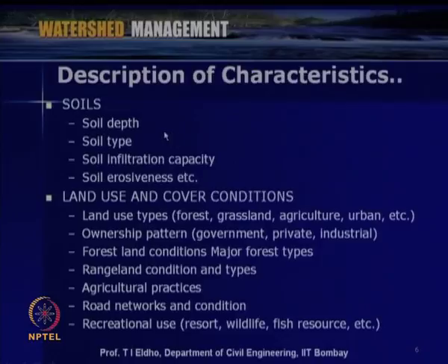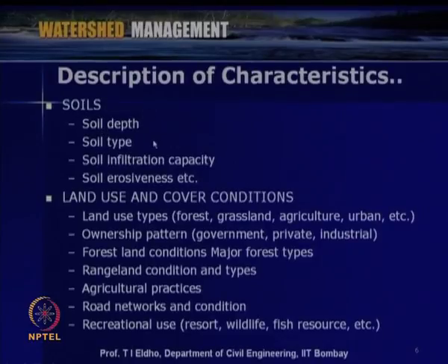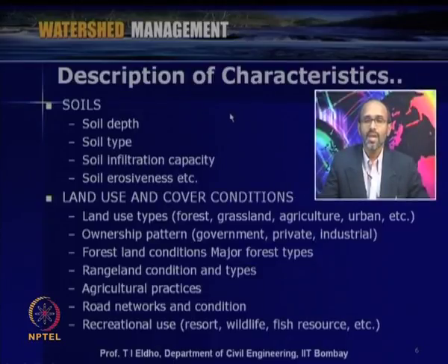So, geological parameters are also very important when we deal with watershed modeling or watershed management. Now, as far as soils are concerned, what is the depth of the soil within the watershed? That is very important, since accordingly the agricultural activities and the infiltration parameters will vary. Then what is the type of soil, whether it is sandy, loamy or clay.